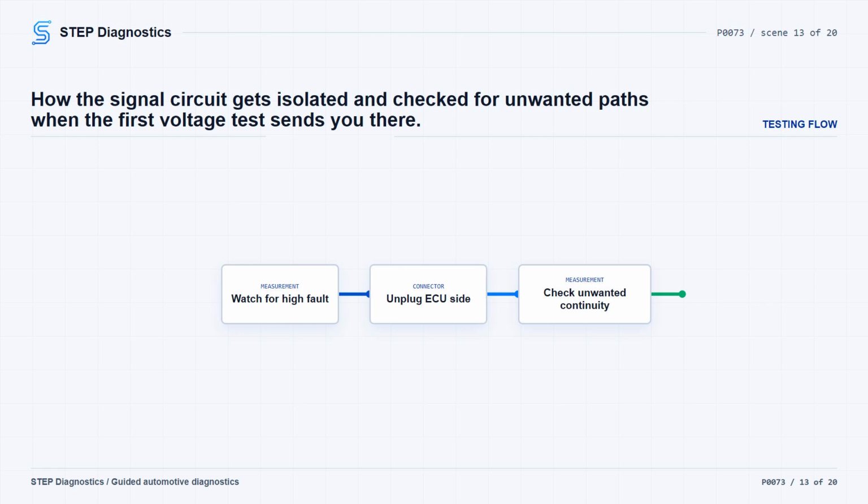If that signal circuit checks good, inspect all connectors in the system for pushed out, spread, corroded, or dirty terminals before condemning the ECU. To check the temperature sensor side, move the test lead over and backprobe the temperature sensor ground circuit at the sensor harness connector.